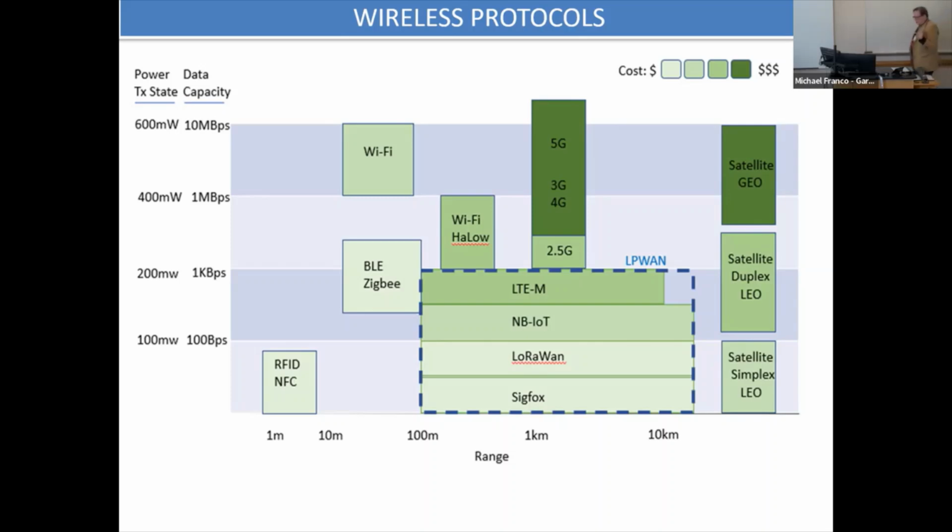So these are the protocols I focused on. I focused on what they define as narrowband. These all sit below 1 gigahertz. There's a mixture here. These two are cellular, and these two are using unlicensed RF spectrum, what's called ISM, instrumentation, scientific and medical, which means free. It's free spectrum. They don't pay for it. Now, with cellular, you're obviously paying an account for use of cellular.